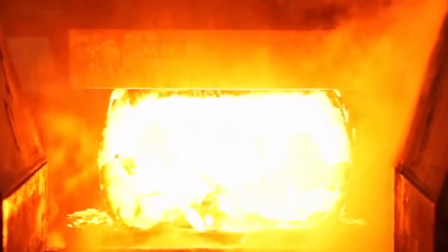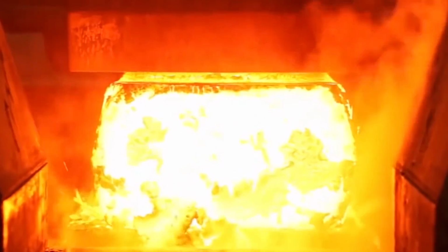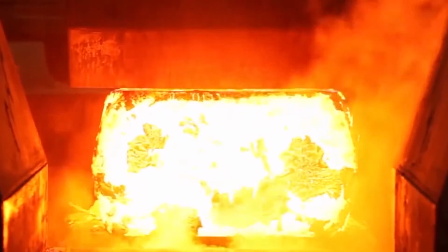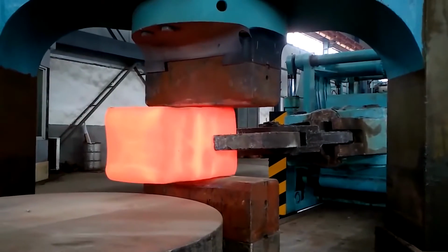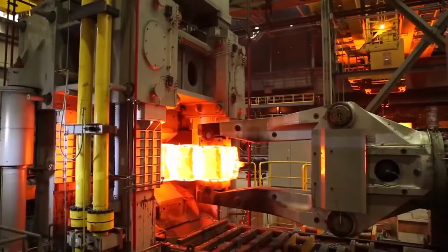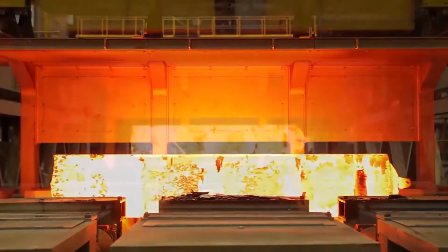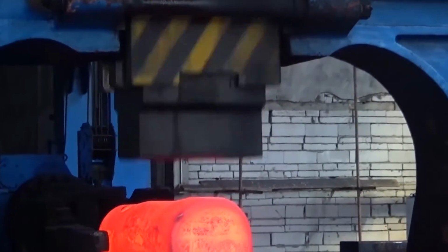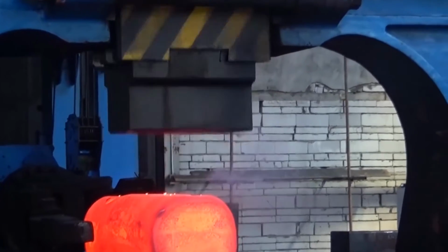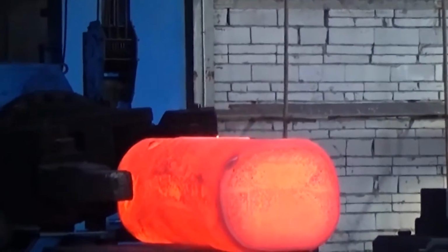For example, the blacksmith's press shown in the video hits the metal with a pressure of a little more than 3 tons. In another case, the metal is hit by a hammer whose weight is 20.5 tons. It is clearly seen how under the influence of the impacts, the piece of hot metal becomes smaller while maintaining its original mass. When this happens, the atoms move within the material. They move relative to each other by an amount greater than the interatomic distance.